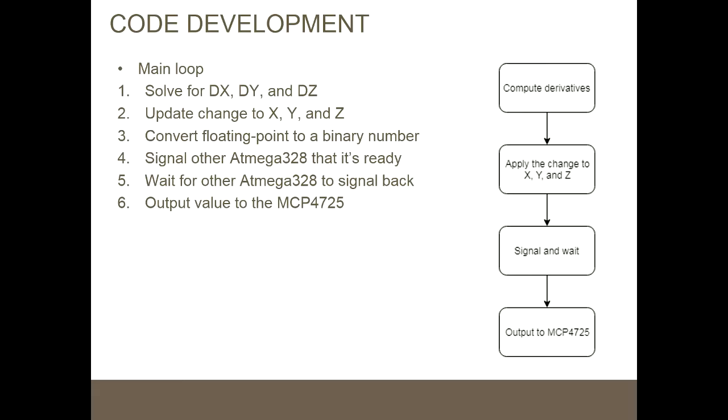All I did was just add them together. Now there are 3 major operations that I need for the IEEE floating points: addition, subtraction, which I put along with addition, and the big one was multiplication. Addition and subtraction is very straightforward. You just match the exponents, then add the fractional parts, normalize the fractional part, and then adjust the exponents when you normalize it.